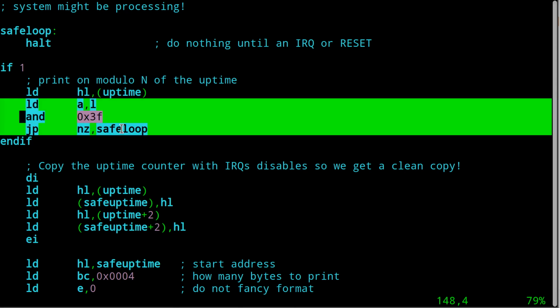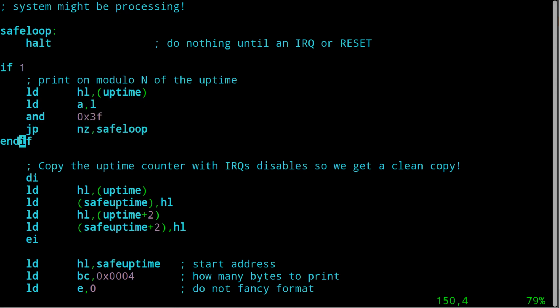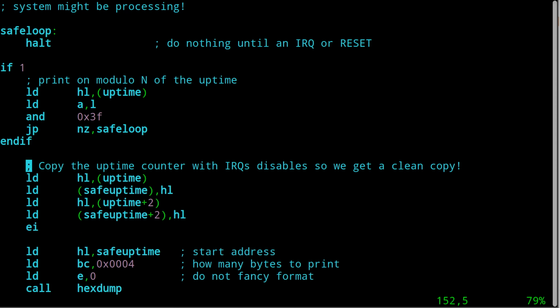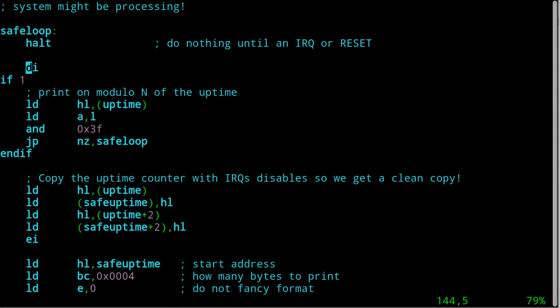So let's actually fix it the right way. I probably should have done this in the beginning. What you need to do is disable interrupts up here and say, look, the critical region starts here. Check it. Is it what I want? If it is, fall through, make the full copy, re-enable interrupts down here, and go on our merry way. In this version of the code, this load here is not needed anymore because it is redundant with the one up here. All right, there are some optimizations maybe we could do here.